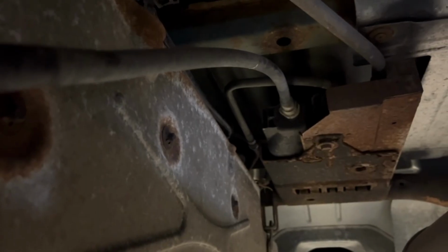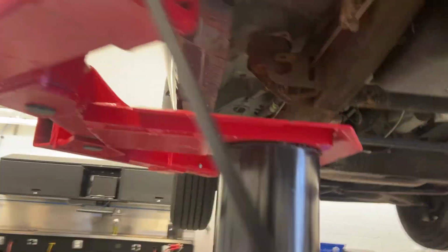So here we took the line off of our vent valve, have our smoke tester hooked up to it, going into our canister, and we hope to see smoke come out on the top side of the fuel tank, or our fuel filler neck. Smoking from here with the gas cap off, we were unable to find any smoke coming out of the gas tank as it should have been. So now we're going to try smoking the gas tank and going backwards.